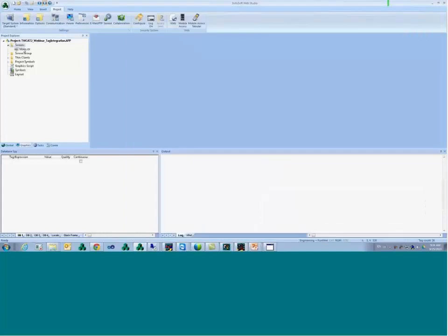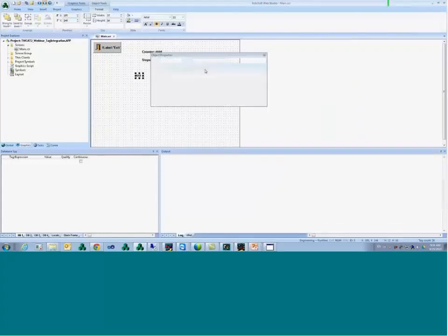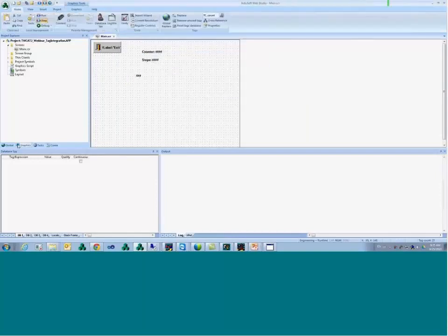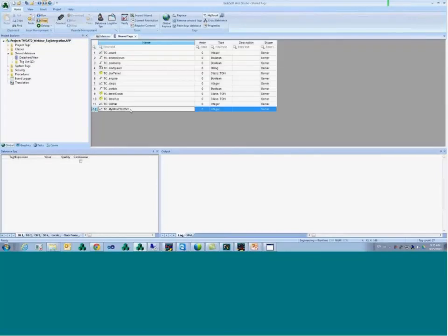So if I go to my tag integration now and try to connect to that file, I do have my struct test showing here. It shows as a separate folder, and I have the variables here. So I can import, for instance, my member M1. So I just imported it. When I look on my shared tags database, here's my tag M1, but that's just an integer. I didn't import the whole structure.